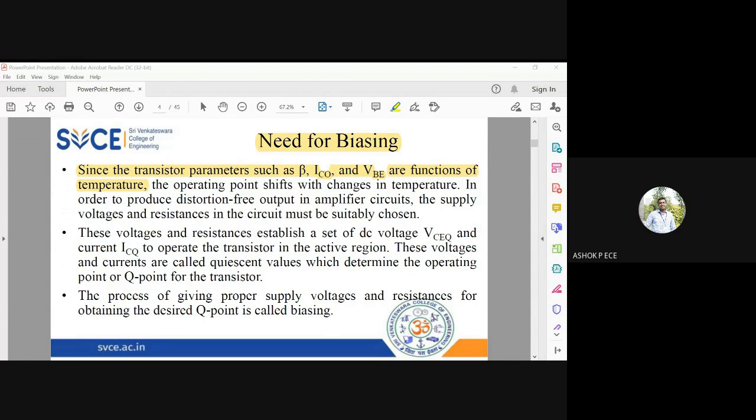So that is going to be the forward bias voltage. Until you give 0.7 volt to a silicon diode, the diode will not conduct, because already you have 0.7 volt inside. Only when you give a voltage more than 0.7 volt does current start flowing in a forward biased PN junction diode.